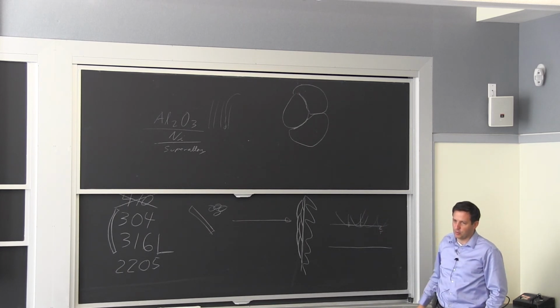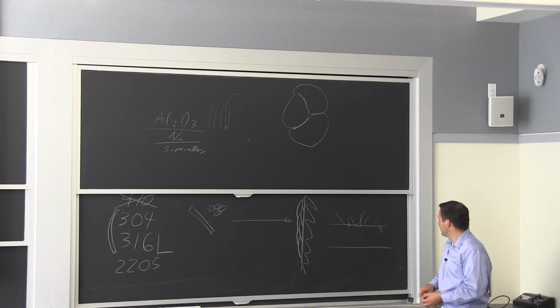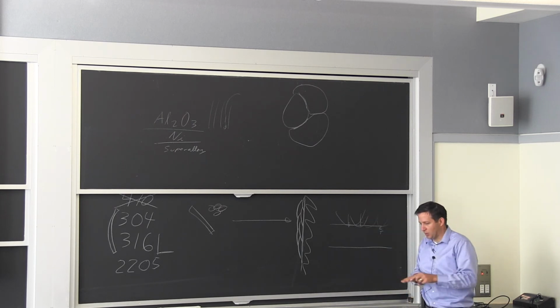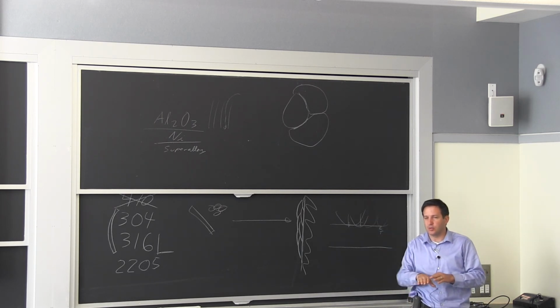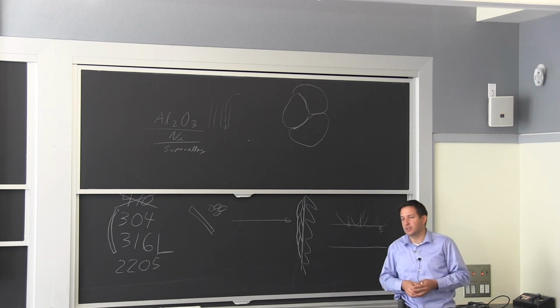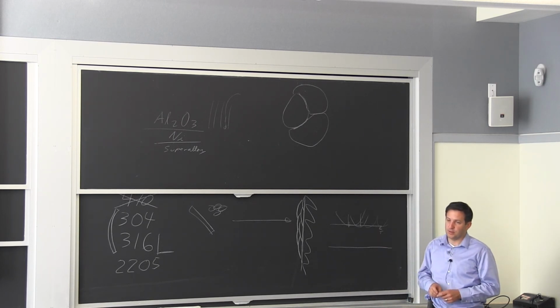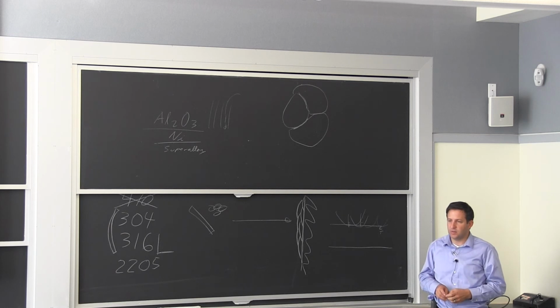That's free body diagram. You start with no stress. You come and you hit the surface. So by plowing the material, you try to expand it. And when it's unloaded, it's trying to come back. It can't, so it's in compression. But what you did is you did stretch permanently what's underneath of it. The main reason for doing this is fatigue resistance.